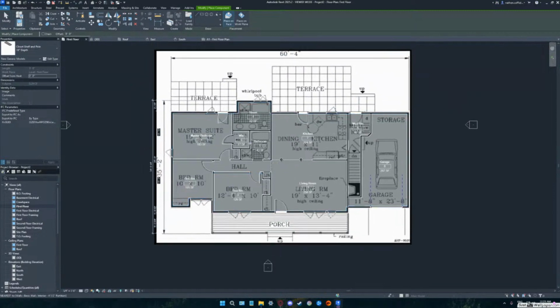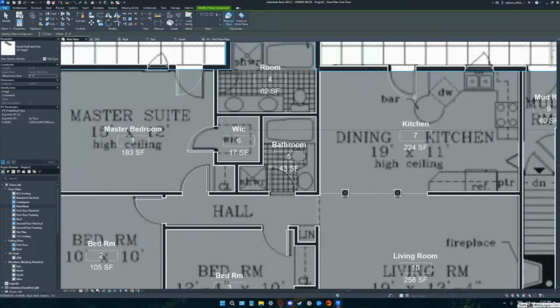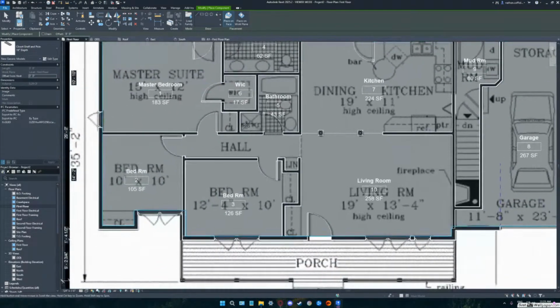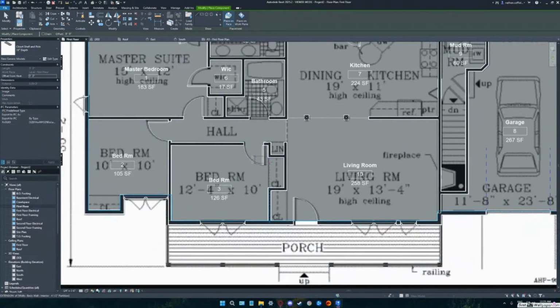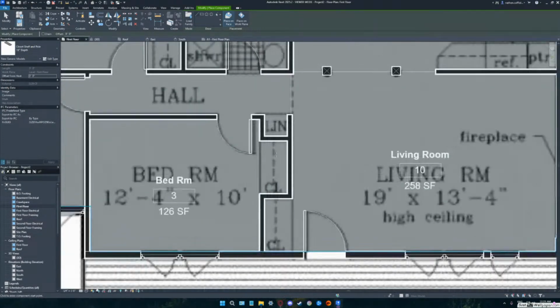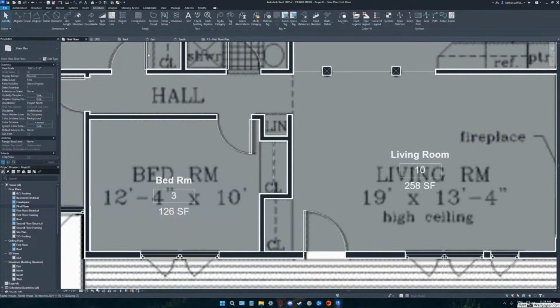And what you do is, I think you draw that one as line based. Don't do the U-shaped one. Do one of the simple ones, one of the little closets, one that's just a straight line. Right here. Yep. If you just trace the back wall, I think it wants you to pick the 2 back corners. Pick and pick. And right here, see, that put that little rod in there. If you went and looked at it in 3D, you would actually see what it looks like.